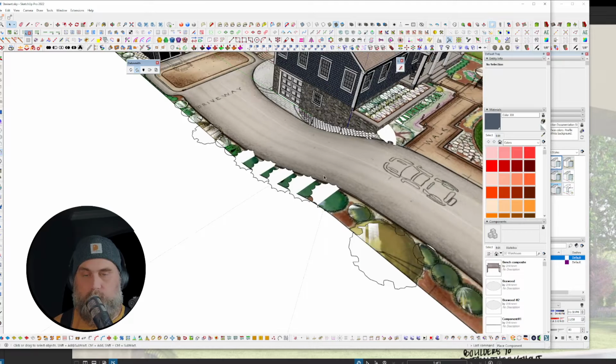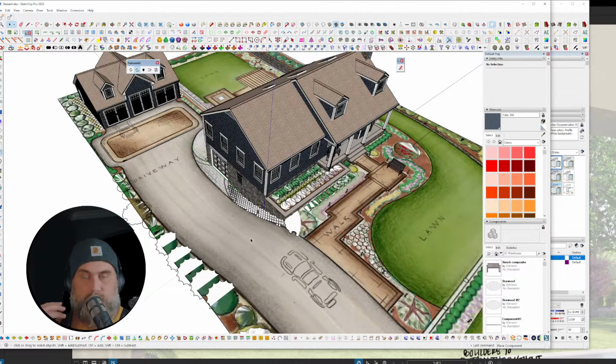Basically what you want to do in Twinmotion is there's 3 different kinds of import options. One is keep hierarchy, one is collapse by material, and then one is collapse all. So for landscape designers using Twinmotion, here's the way that you would think about that. Collapse all is for imported 3D plants or imported 3D models, furniture, any of that kind of stuff.